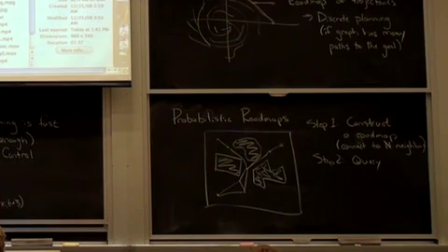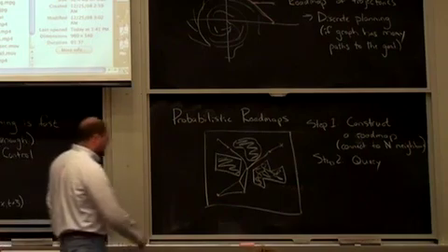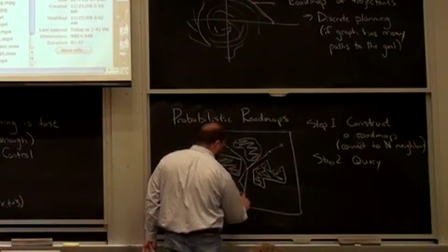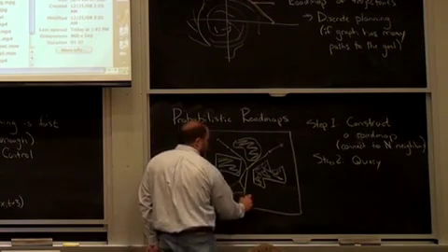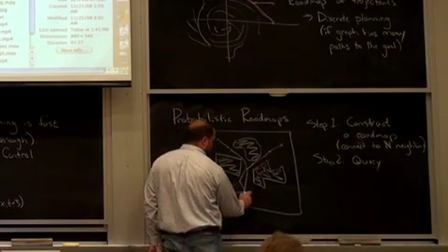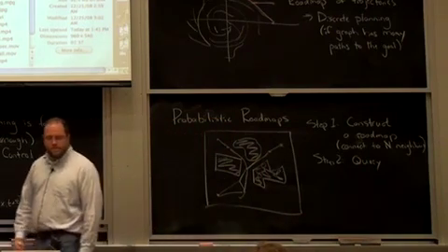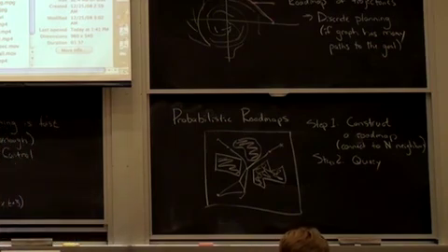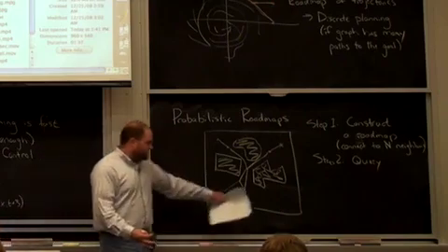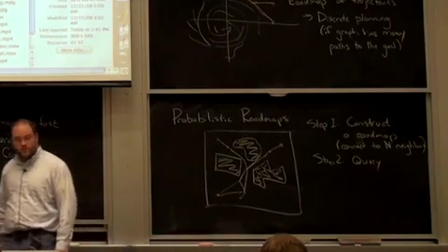So when the query phase comes along, again, all you need to do is connect to your roadmap. I get a new query. I just connect to my roadmap. I do whatever my discrete searching problem, my A star or whatever, to find a path from the start to the goal. Okay? I actually think it's a very beautiful idea to sort of have this web of possible trajectories covering the state space. And then all it takes at execution time is connecting and then executing your trajectory.